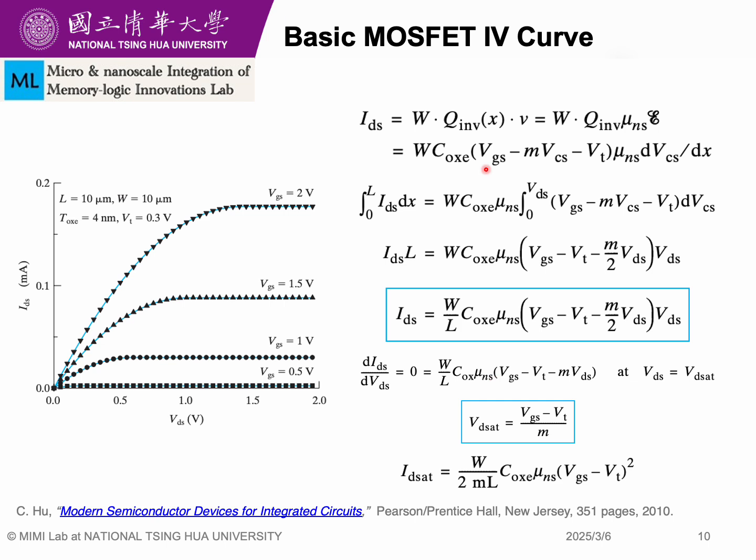So now the MOSFET has two operation regions. One is the linear and another is the saturation. In the linear region, the transistor behaves like a resistor, and at saturation, IDS becomes constant and independent of VDS. When VDS equals VDSat, the inversion layer at the drain end of the channel disappears. It's called the channel pinch-off. Beyond VDSat, a short high-field pinch-off region exists where the inversion charge is 0, and the voltage is dropped across it.